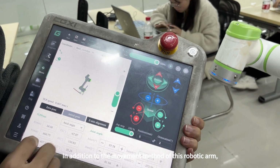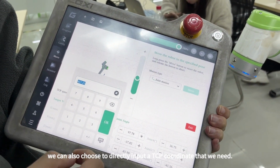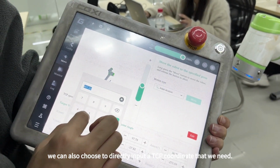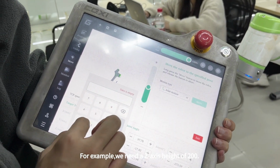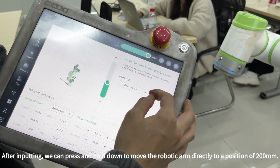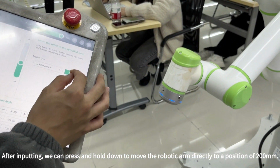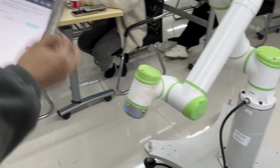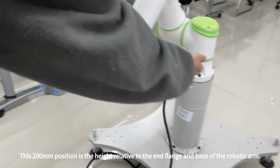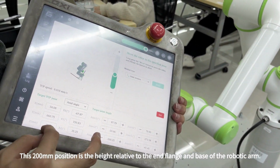In addition to this movement method of the robotic arm, we can also choose to directly input a TCP coordinate that we need. For example, we need a z-axis height of 200. After inputting, we can press and hold to move the robotic arm directly to a position of 200 mm. This 200 millimeters position is the height relative to the end flange and base of the robotic arm.